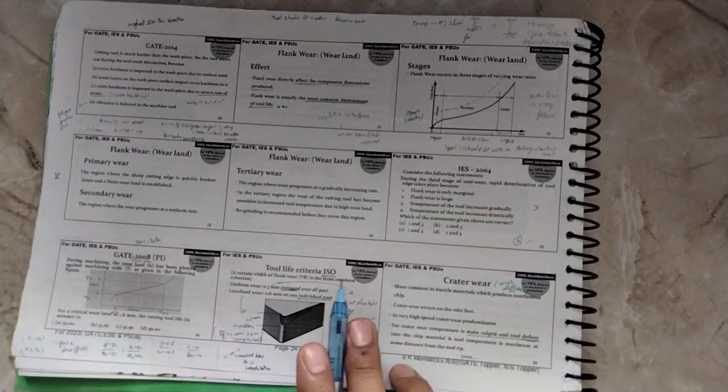I think you are able to see this one. Generally, mostly failure will occur with the flank wear only. So the rake surface, definitely wear will be there, but the flank is so much more important. I think you can easily measure this one, x2 minus x1 and y2 minus y1. To find this one, y minus y1 divided by y2 minus y1, or x minus x1 divided by x2 minus x1. So based upon this you can calculate each and every thing.